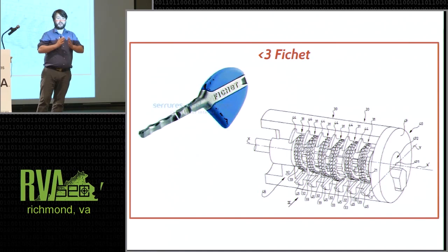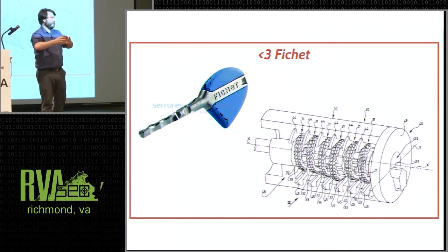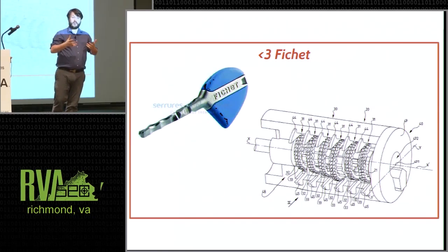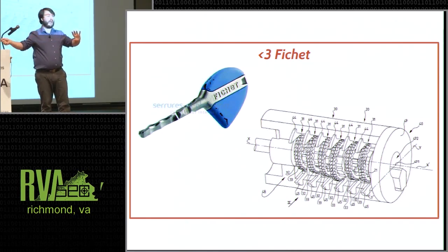The way they build the difference in is that they slide the key into the lock and then put the sidebar wafers on, so that whatever position all of the gears are in, with the key inserted, is the open position of the lock. They then slap the sidebars in, remove the key for the first time, and everything is scrambled to the now unlocked position. And as a result of that assembly process, they were able to patent protect their key, making an end run around the French Patent Office.